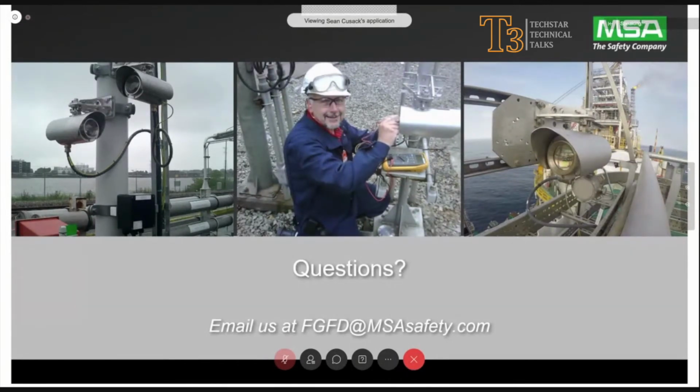Can SO2 be picked up with H2S or cause interference? No, it cannot, and it will not. Can a detector differentiate between multiple hydrocarbons that may have similar 2nd, 3rd, or 4th harmonics? No, again, it's fingerprint specific. The only hydrocarbon gases that we can currently do are methane and ethylene. The fingerprints are a little more challenging than something like propane. You'd have to use something of a wider band.